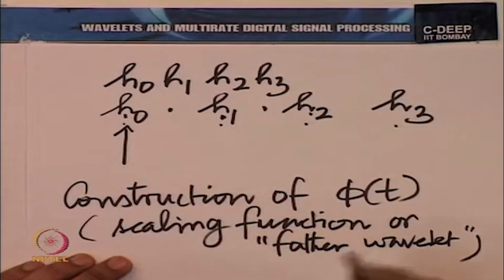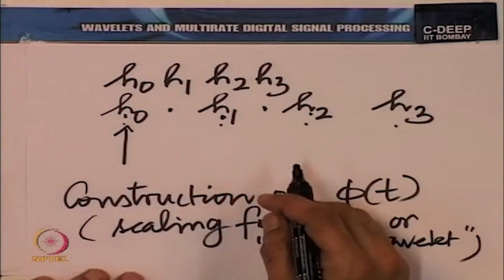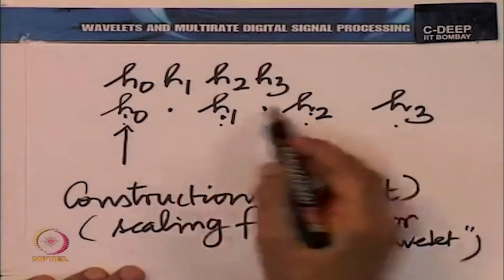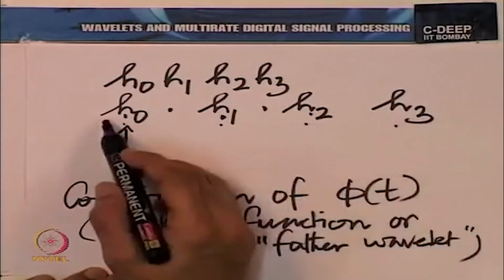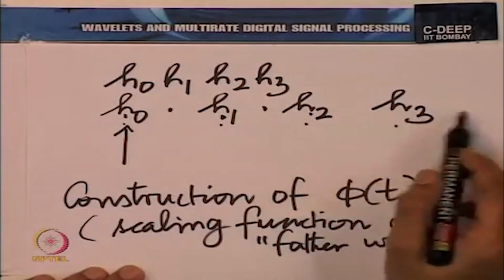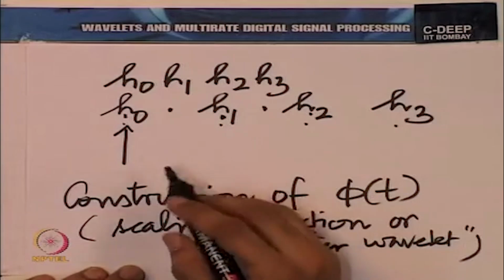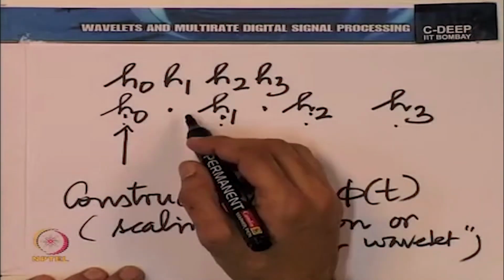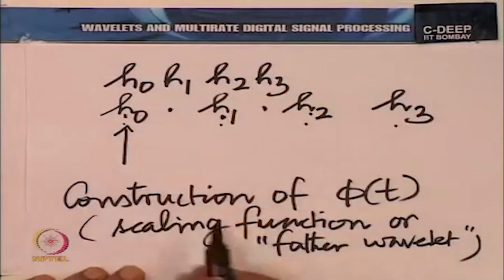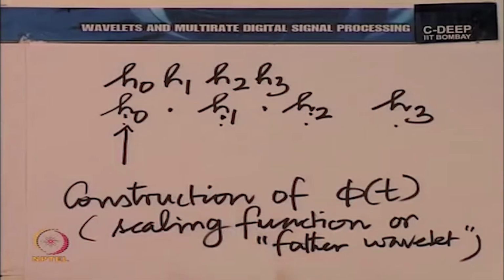So, it is an iterative convolution, and you can visualize that you would get impulses in one step of this convolution. From 4 you would get 8, and in fact, this would stretch a little beyond, as you can see. In the next one you would again get this squeezed by a factor of 2. Now, in this case it is much more difficult to visualize where this convolution is leading. What I have given you is the mechanism, and in fact, it is a very important exercise, a simple, but a very effective computer exercise in this course to actually carry out this convolution.